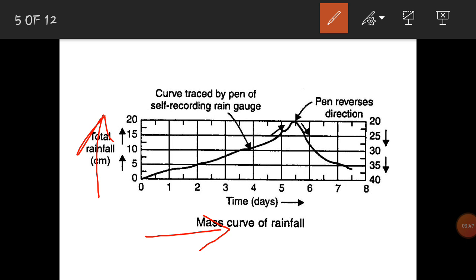So there are instrumental errors, errors in scale reading, dents in receivers, and dents in measuring cylinders. About 2.25 mm of water is initially required to wet the surface of the gauge. There is splash from collectors, frictional effects, and non-verticality of the measuring cylinder; a 10-degree inclination gives 1.5% less precipitation.